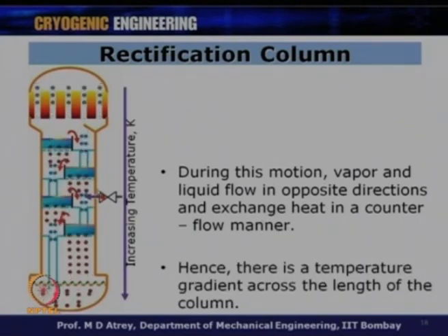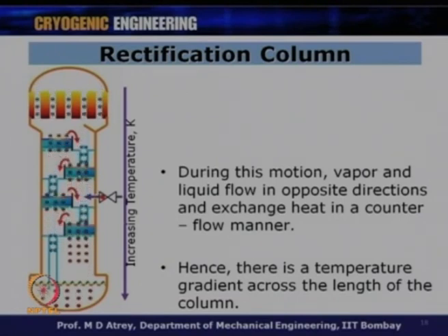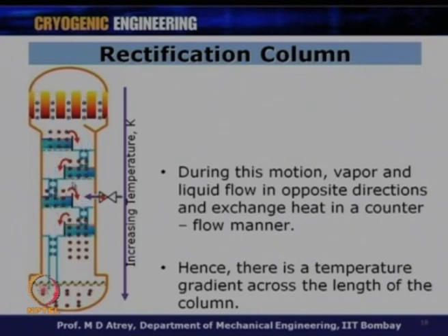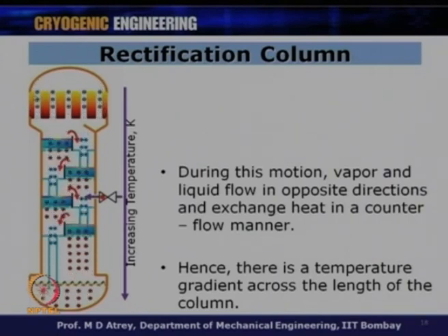When the vapor or the vapor liquid mixture enters, the vapor passes through the liquid, and this liquid above this plate is going to be at a lower temperature, and therefore, the heat exchange happens between the vapor and the liquid. The high boiling component in the vapor will get condensed at this point, while the low boiling point components of the liquid will get evaporated, and ultimately the low boiling component vapor will go to the top, while the high boiling component liquid will come down.